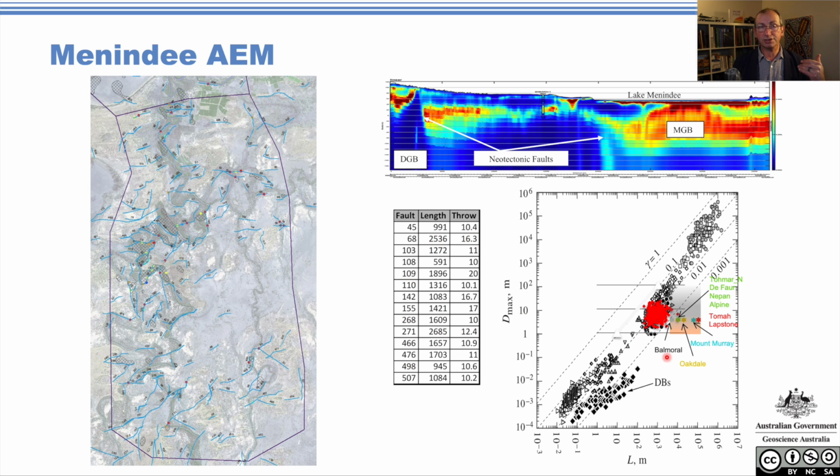These are large faults, crustal faults from outcrop mapping, but they sit in a sensible range. There was debate about whether these were monoclines, actually folds rather than faults. And if you've got folds, then you wouldn't have juxtaposition windows. So we've plotted a set of monoclines from the Sydney Basin to show they have a relatively long length for their fold displacement, and they sit outside of the fault range that the guys at GA picked. So these look like faults.